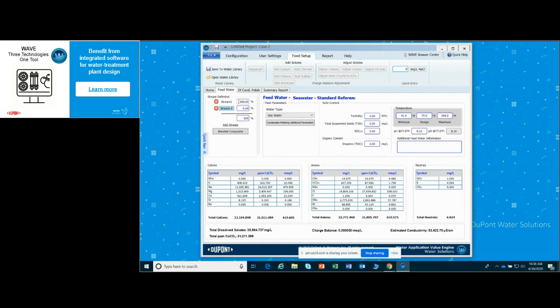Now you specify how much of each you have. We're going to say we have a pretty small leak, which turns out to be only about 0.005. That's fair. And then we'll come up here and we'll put in 99.995. Condenser leaks are pretty small, so they get rounded off, but it will, in fact, use the digits you can't see to do that.